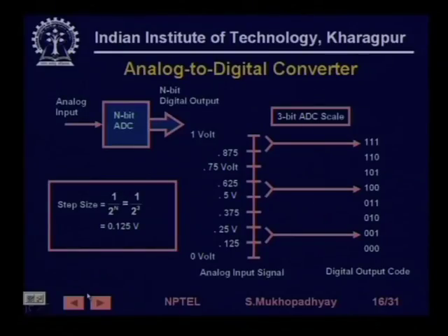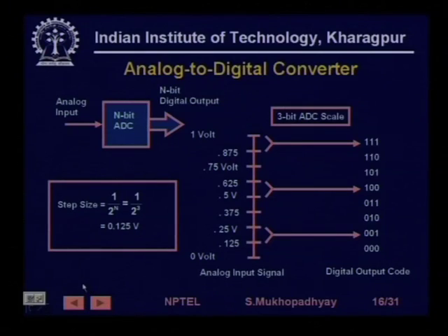If you do not do that, then your AD converter, just because of noise, even if you present a constant signal, its digital bits will start oscillating, and the last few bits will anyway be useless because of noise. So, that is why it is very difficult to construct AD converters with number of bits more than 18 maybe, and generally for this kind of thing 12 to 16 are used, 12, 14 or 16.